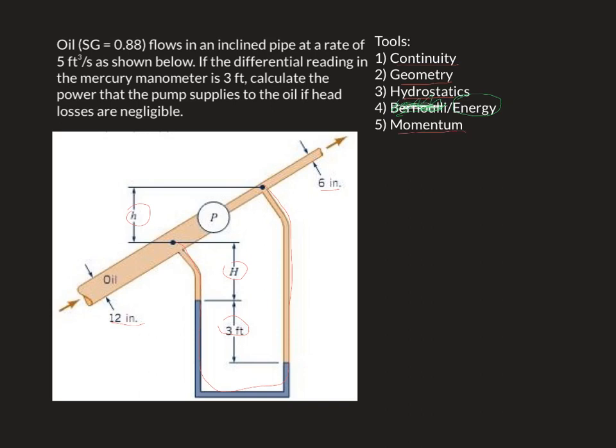Okay, what about momentum? Are we asked or told anything about forces on a moving fluid? No. And you might say, well, what about the pump? You could think about the pump, but we're not asked for the force of the pump. We're asked about power. When it's power, we always think in terms of energy.